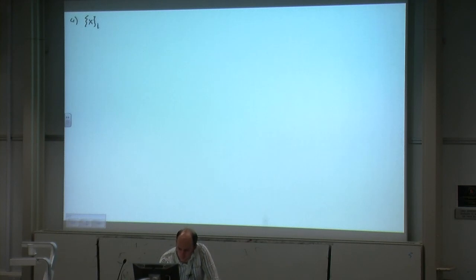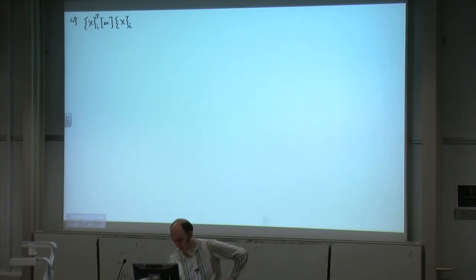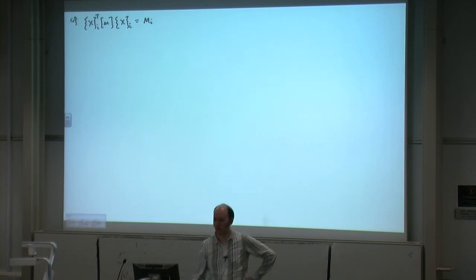We then start step 4, which is to find the modal masses. And the equation for the modal masses is, I'm going to call this mode shape i, it doesn't matter, times your mass matrix, and that's transposed. And that equals mi. This is the equation that you need to use for the modal masses.